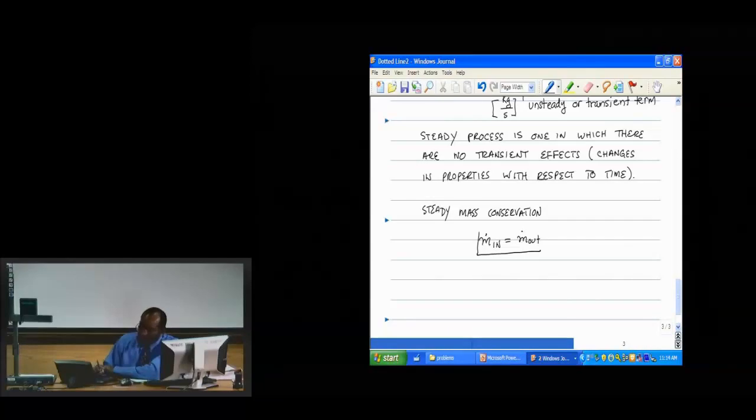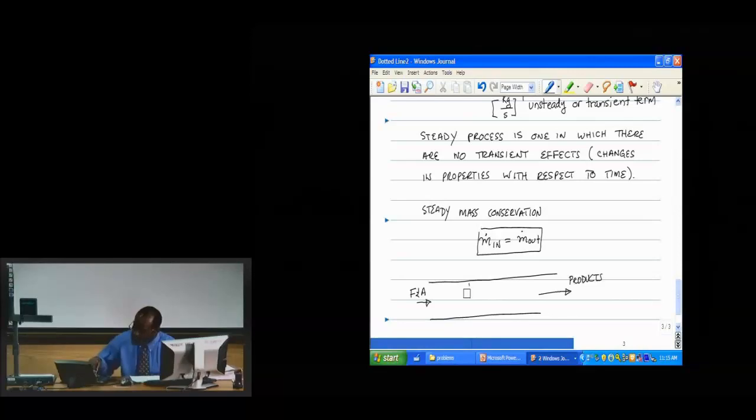So we said, what's a flame? A flame is an interface. And a premixed flame is an interface between reactants and products. So imagine that you have, again, this pipe where on one side you're flowing in fuel and air, so a reactant, and out of the backside, you're flowing out products of combustion. So this is some reactor. And for fun, we put our control volume surfaces over here.